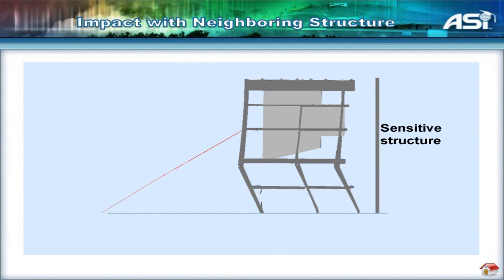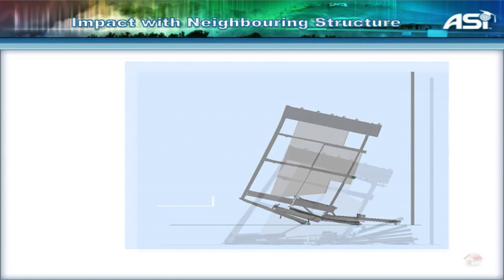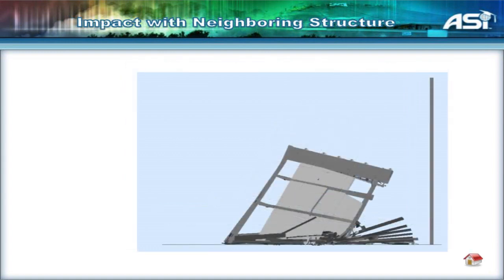Another case. Now the same structure is falling the right way. We got it to fold the right way. So it's moving forward. We changed the scenario, and it's moving forward nicely. But what's the problem you see here? The problem is this structure had the top beam, instead of being supported by the structure, actually supporting the whole structure. The top beam was acting like a support, and everything was hanging from the top beam. I have a slide later that shows that. So they had those hangers here, and the whole structure was hanging from this very heavy top beam. So the problem was this top beam separates.